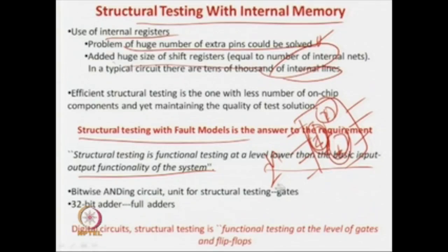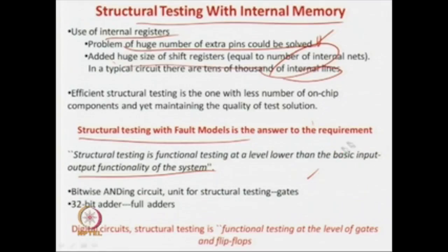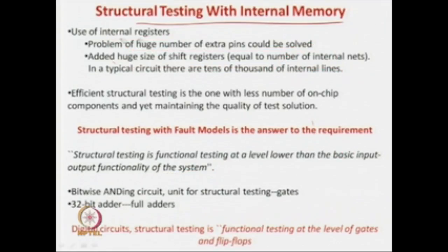In general structural testing, the term we use in testing, the basic block levels are the gates, and sometimes we can go up a bit higher. Like in the previous example, our unit was a full adder. We were not going inside the adder to test it, but rather checking that structurally the interconnection should be fine.